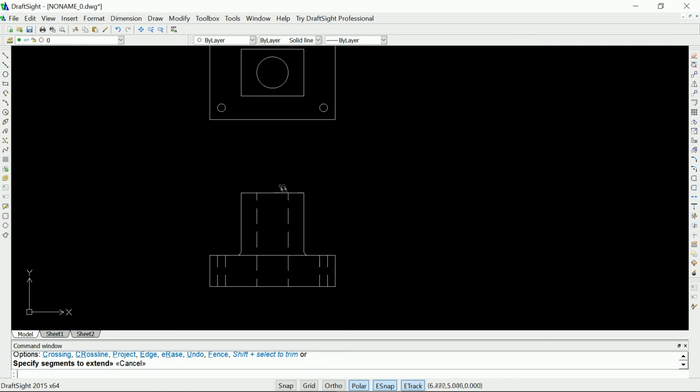But right now we're going to just leave off the chamfer. And we're going to call this good. You can add your center line through your holes. So just add center lines through your holes in between those dash lines and one in the center.